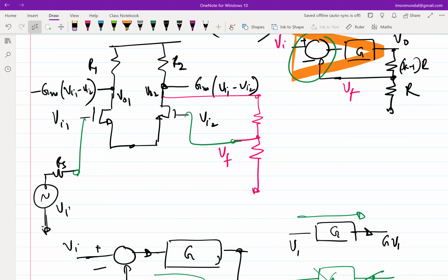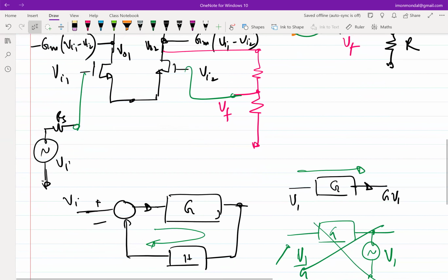You will see later on, it's not perfectly true, but for the purpose of this course, we can assume that a transistor is unilateral. So if the transistor is unilateral, then this whole construct of the negative feedback loop, as we are studying it, is based on the fact that you can calculate loop gain by breaking the loop. Then you have to break the loop in some place which is one, unidirectional, and two, not loading. If you don't consider the effect of loading, then you will have a problem.